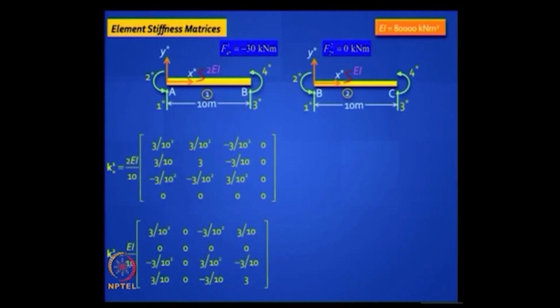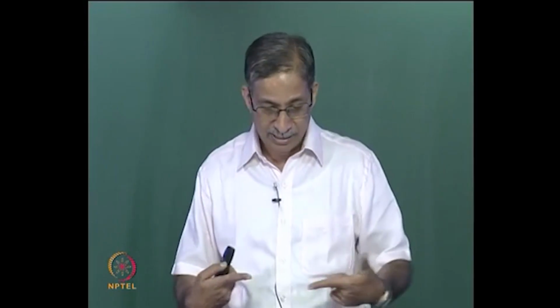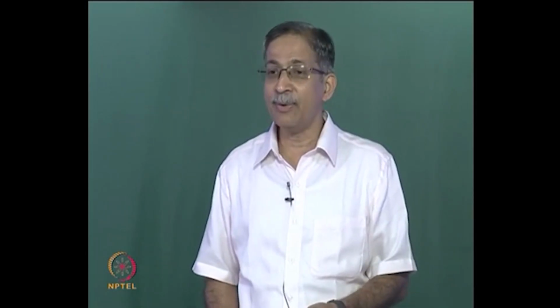This part you can generate, remember those formulas which we generated for the 2 elements. Can you generate the element stiffness matrices? Then can you multiply them with the identity matrices and put the linking coordinates, and you assemble the structure stiffness matrices, you will get lots of zeros. Okay, the second row and second column are dangerously 0, but do not worry, they do not belong to the active degree of freedom, so let them hang around there.